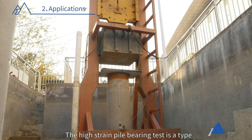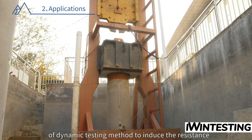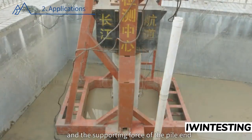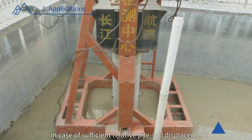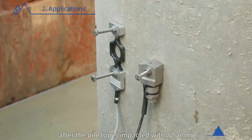The high-strain pile bearing test is a type of dynamic testing method to induce the resistance of the surrounding soil and the supporting force of the pile end in case of sufficient relative pile soil displacement when the impact pulse is spreading downwards after the pile top is impacted with a hammer.